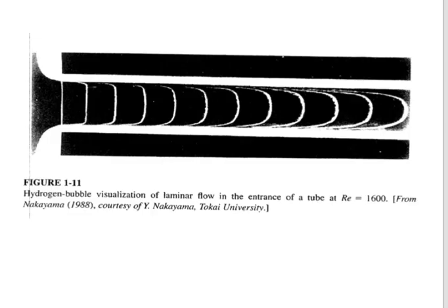If you see the example of the hydrogen bubble visualization, you find it can be shown that at the entrance here, there is resistance on the pipe wall, which makes the velocity not moving. The molecule is not moving. U is equal to 0, and then the shape keeps continuing like this, and at one point the maximum velocity is at the center line of the pipe. So this is the behavior of flow in a pipe.